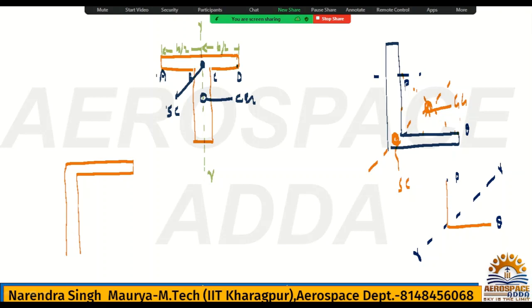I will show you for the channel. Even if you calculate x bar and y bar, you will get here, because it is not symmetric about the x-axis and not symmetric about the y-axis. For any structural member which is not symmetric about the x-axis, nor about the y-axis, the CG will not lie on the x-axis, nor on the y-axis. It will be in between. That is the definition.